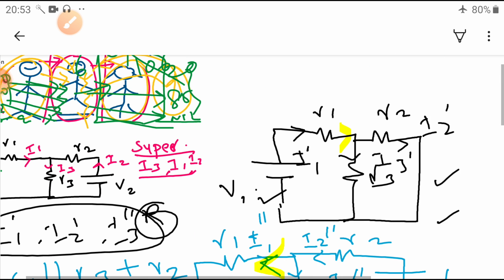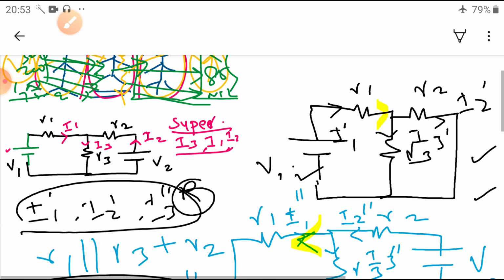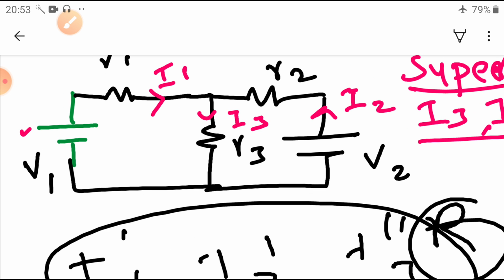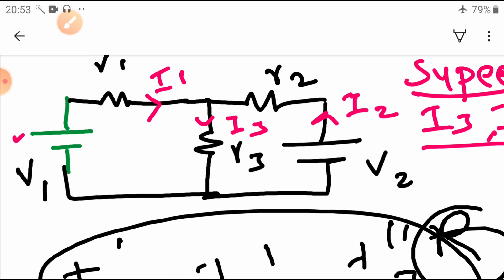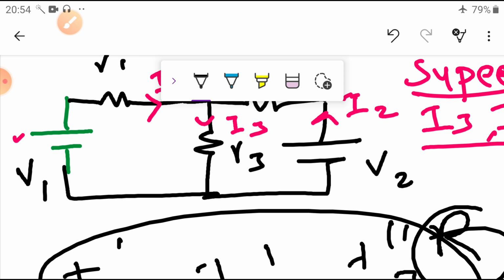Okay. Dear students, what you have observed once again, this is the given circuit. So, in this circuit, here we assume two sources. Suppose 3 sources are given, then you take it 3 times. If 4 sources are given, 4 times. Whether the voltage source or current source is given, simply apply the current source and voltage source one at a time. Whatever the source, it may be current source or voltage source. If the current source is given, simply open the terminals. For example, okay.